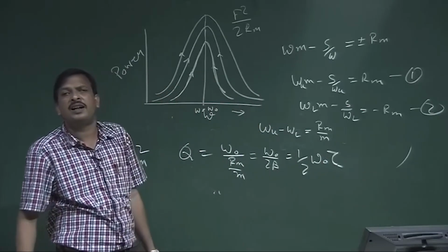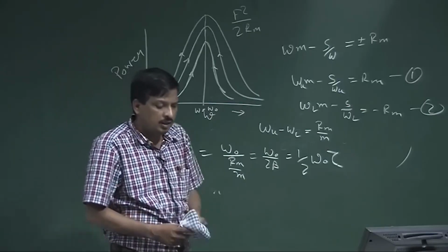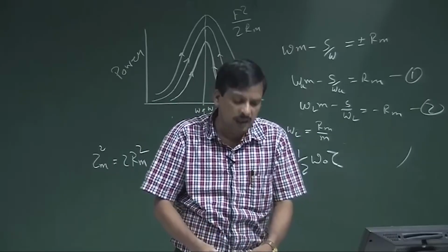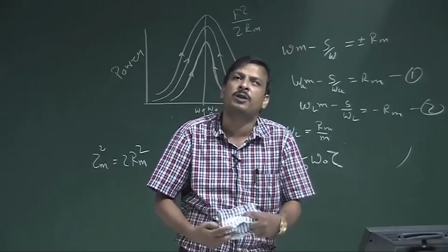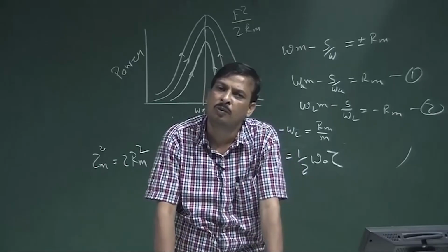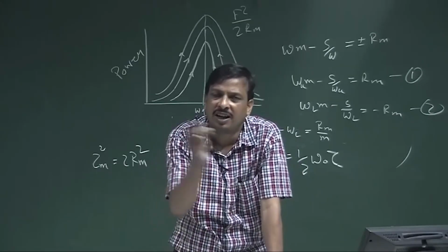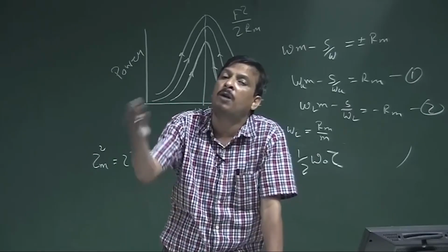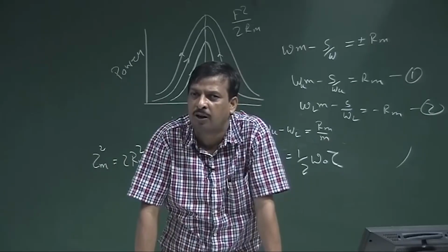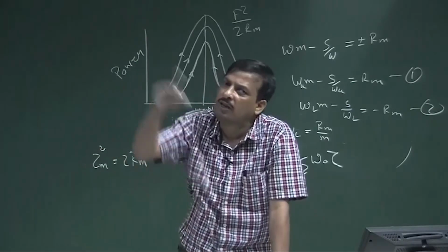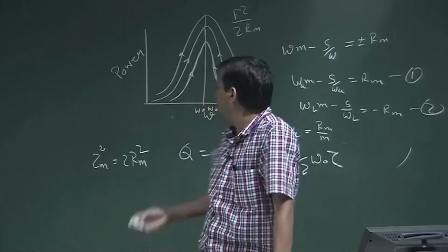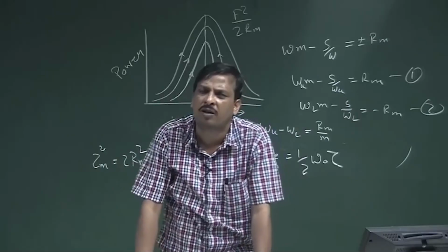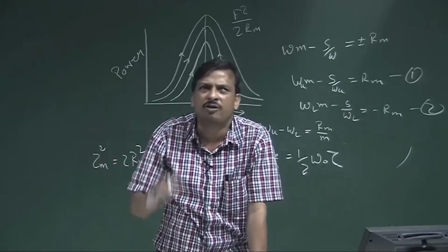Okay. So, this is called mechanical resonance. Now, why is it required? Suppose I want to design a microphone. If I operate a microphone at the resonance frequency, what will happen? The diaphragm will break down. So, I have to design it below the resonance frequency, and I have to know the power transfer at that point. So, I have to draw the power curve of that diaphragm and know its quality factor. I can easily calculate the quality factor of the power curve. That is why this theory has to be known.